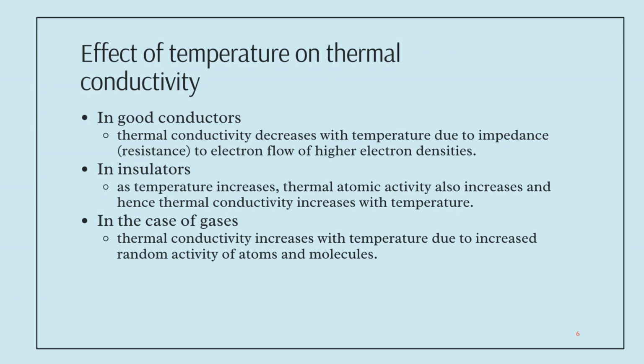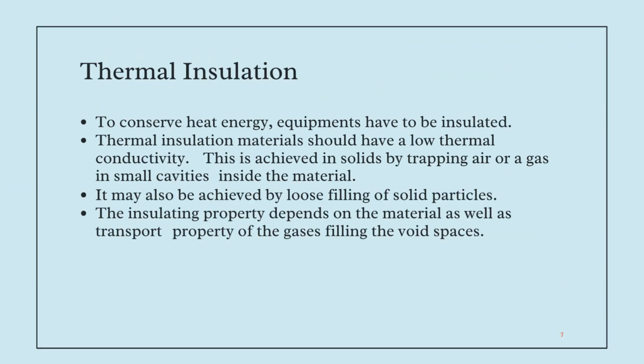Moving to next slide. Thermal insulation. To save heat energy, equipment must be insulated. Insulating materials should have low thermal conductivity. This is achieved by trapping air or gases in tiny spaces inside solids or by using loose solid particles. The insulating effect depends on both the material and the gas inside.